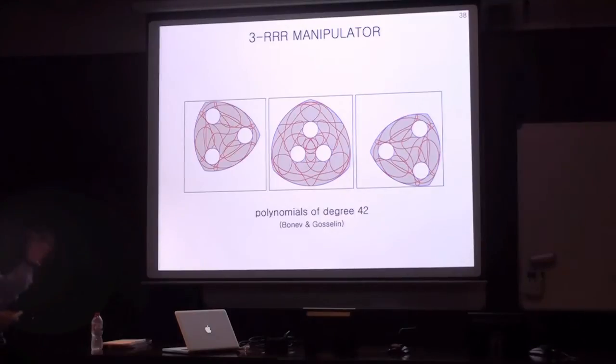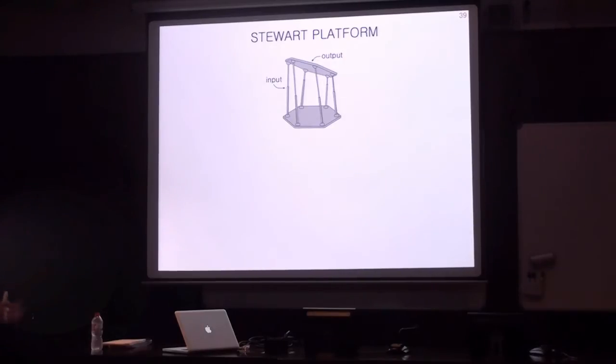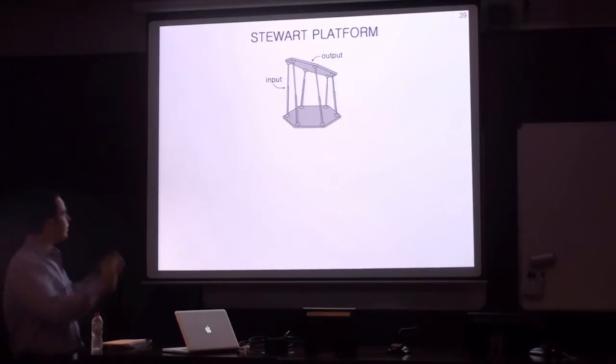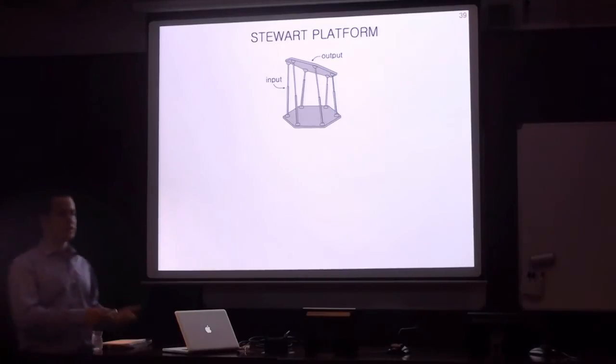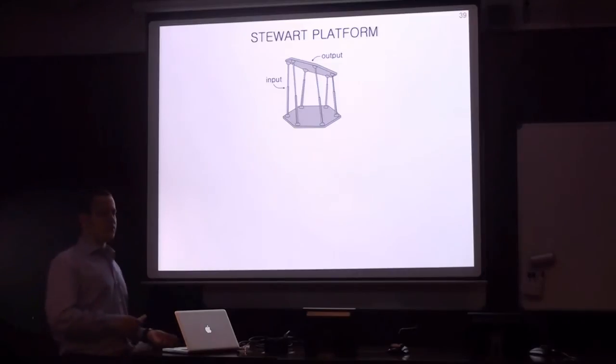To see how the method works in spatial manipulators, we can compute some singularities of the Stewart platform. In this manipulator, the most important singularities are the forward singularities, because in the majority of designs, the limits on the joints do not allow the appearance of inverse singularities. But if we had a design that allowed the appearance of inverse singularities, we would be able to compute them as well.